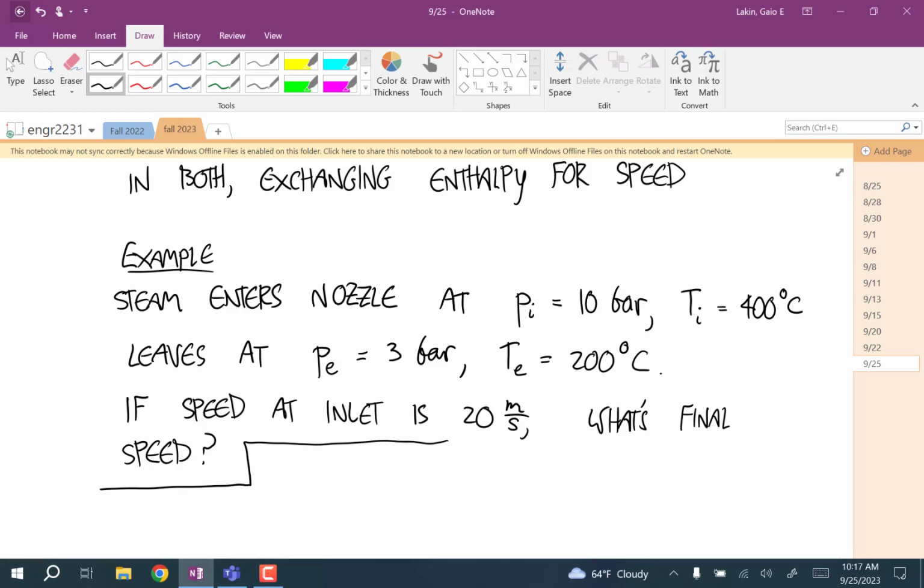Okay, well, we're starting with a superheated vapor. How many properties do you need to know the other properties in a superheated state? 2, right, and we have them, pressure and temperature. The fact that the properties are pressure and temperature should make it jump to your mind that maybe we're going to use a table. Because that's how our tables are organized, pressure and temperature. They could be organized with any 2 properties, and you can use them that way, but you have to do a sort of painful reverse lookup. It's not the most pleasant thing.